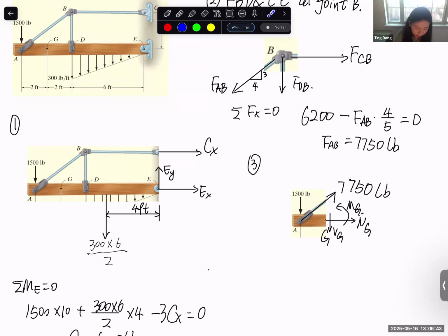It's about, let's say, force applied at the free ends and no force applied in between. So even though at point B you may consider force in this direction, this direction, and this direction, at this one end you already have several forces, and at this other end you also have several forces, like you don't know what force is applied from the A beam to this A point, and also we have external forces. So if you count all these forces, yes, it's more than 2 forces. But what I mean by 2 force is that all the forces applied at this free end, we can combine.